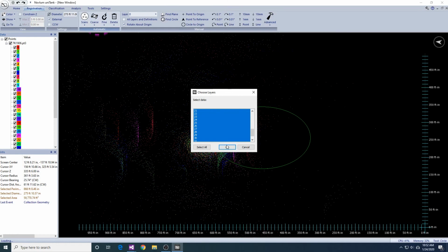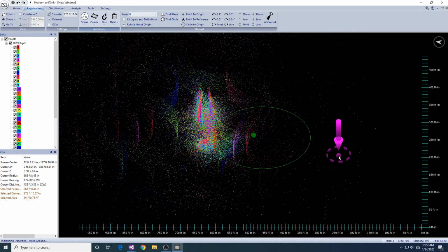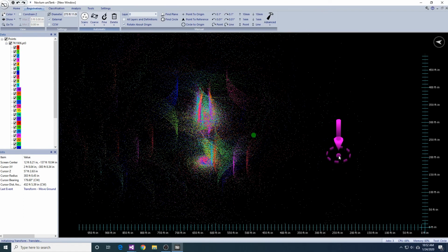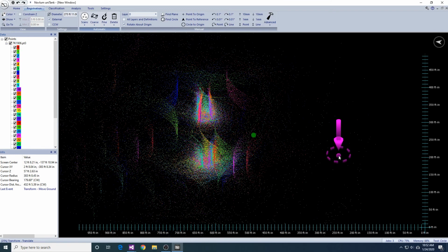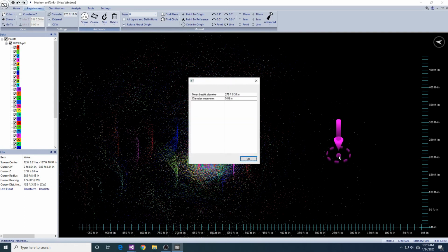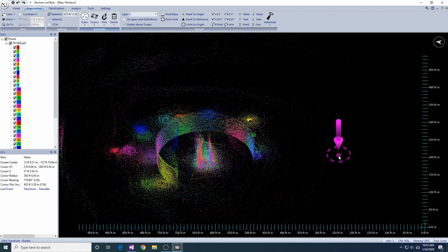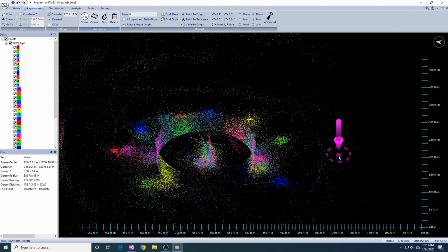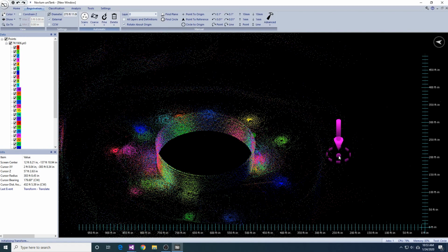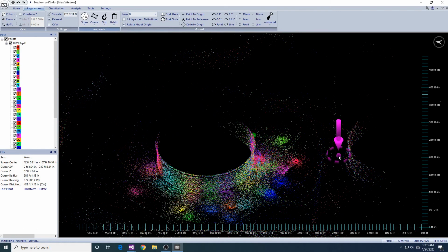Make sure that the Scanned from Exterior checkbox is checked and the tank diameter estimate is accurate. While we wait, I'm going to explain the single versus multi-tank option in the auto registration dialog. The multi-tank option is the better choice for scenarios where there are several tanks within the scan area that have similar diameter. In such a scenario, the single tank option may get confused as to which tank is the tank of interest. We typically use this option for registering berm data. You can try both options and see which one gets you closer to an initial registration.